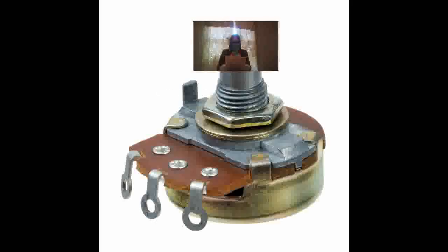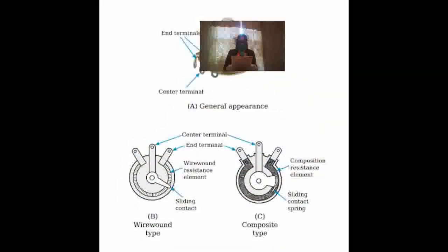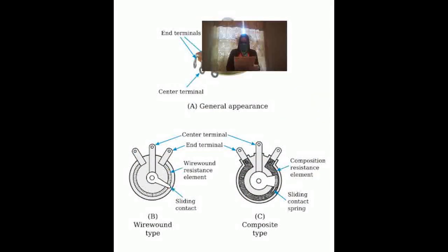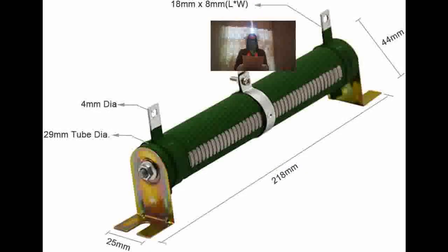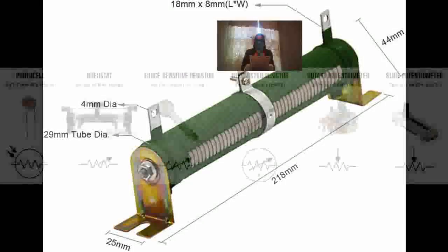A potentiometer is a very common type of variable resistor found on electronic projects. The potentiometer has a rotary knob that varies the resistance value as it is turned. The variation in the resistance is provided by a contact that is attached to a ring of resistive material inside of the device. This device is similar to the wire-wound resistor. Many potentiometers are constructed with thin wire inside as the source of resistance.